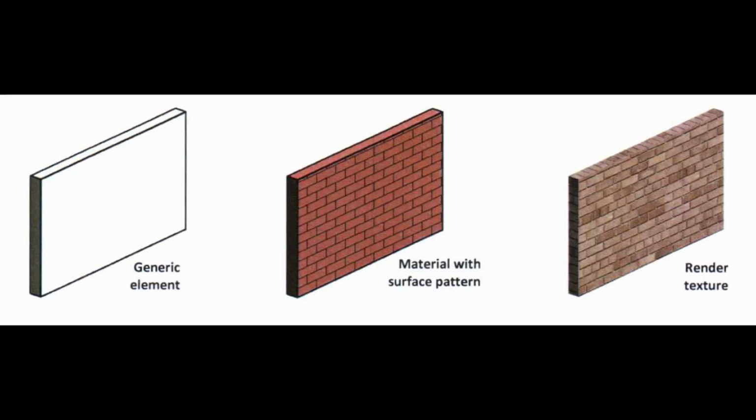Material library, graphics. The material library and render textures serve different purposes. Graphics control how elements look in drawings and shaded views. Render textures are mainly used for realistic visualization. Best practice is to base materials on real-world substances, not abstract labels.